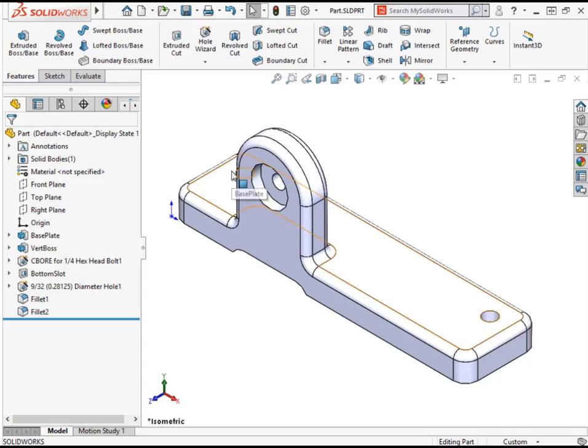The fixture will be added to the inner cylindrical faces of the two bolt holes, simulating the bracket being fixed in place using two bolts. Once the fixtures are applied, an external force of 500 Newton will be applied, normal to this counterbore face of the vertical cap.